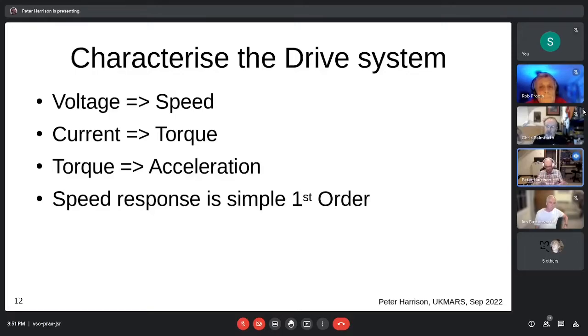Now, we're not going to do the whole maths of motors, but this is the simple way to look at it. So consider, for example, that you have a robot running along on the flat. You fed it with 4 volts and it's doing 1 meter per second. But then it encounters a hill and has to go up the hill. What's going to happen? Well, it'll slow down, because the voltage is constant, but the load is increased, so the speed will decrease.